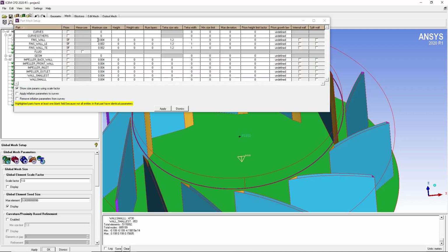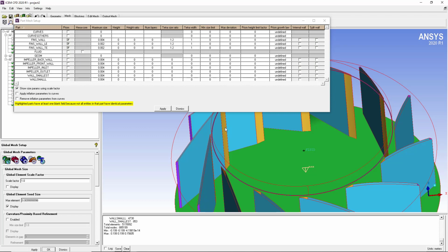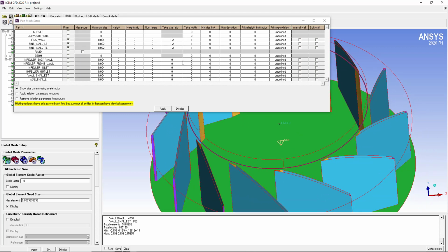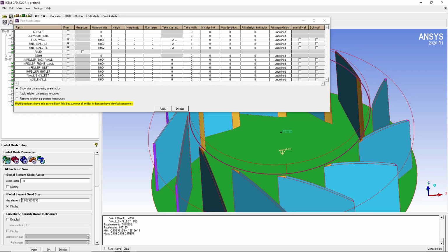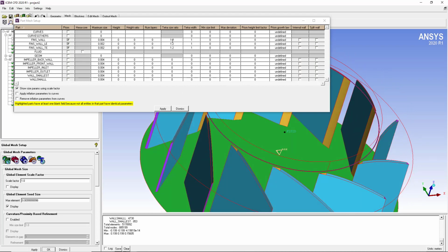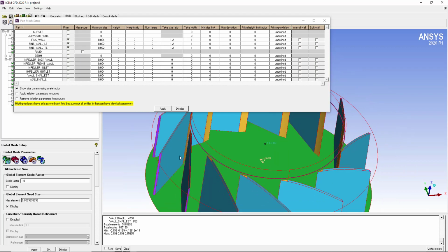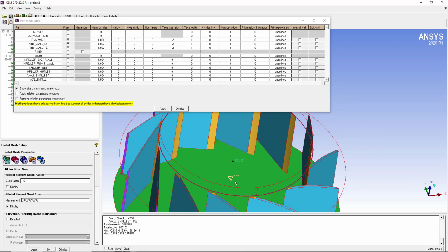And just take a look at these sizes. So for the two sides of the blade, which are leading edge and trailing edge, the size is 0.002, 0.002, and tetra size ratio is 1.2 and tetra width is 1, which I think you have already seen. But just to be clear, the ratio is for the volume elements that they will grow from the surface. After the surface, the ratio is 1.2, and tetra width means that the first element sizes after the surface will have the same size as the elements on the geometry itself. So the first layer will be the size of the surface, and the second layer, which is tetra width, will also be the same size, and afterwards the size will grow at the ratio of 1.2, and by default the growth ratio for the octree is 2, and eventually this will stop at the maximum size.